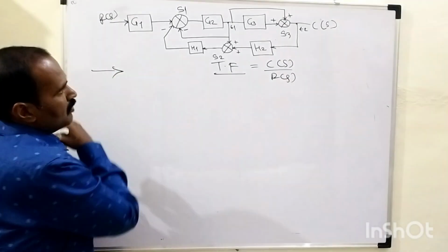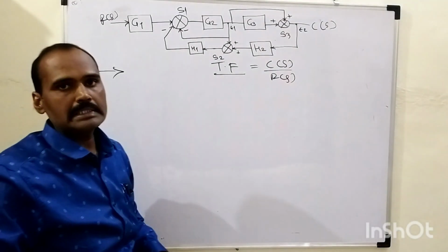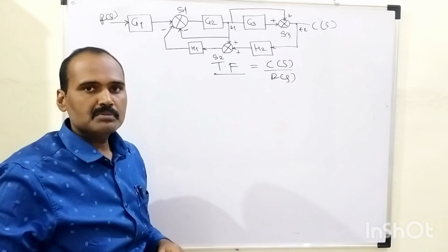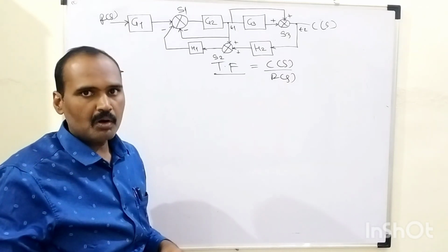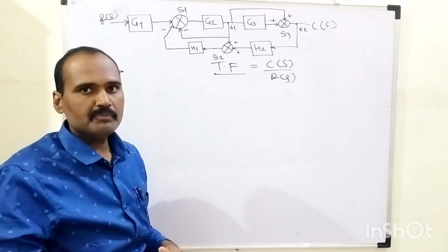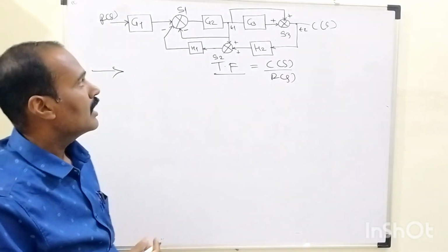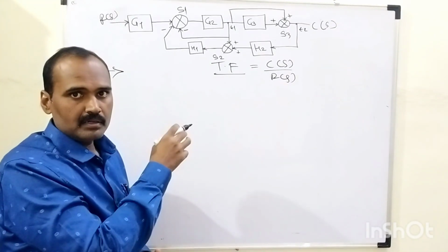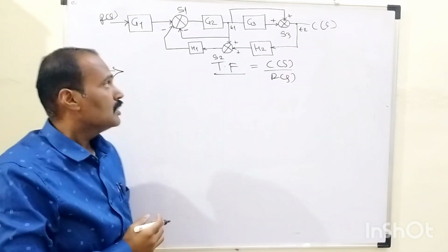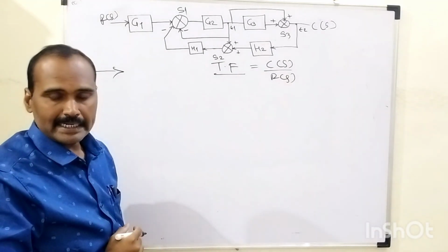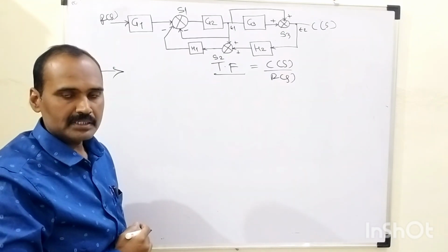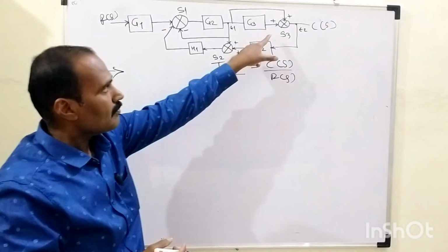So in that first step, what we need to do? We need to map this given control system with respect to those 8 different rules which we had discussed, right? Blocks in series, blocks in parallel, how to eliminate the feedback, associative law, right? And as far as the remaining 4 laws are concerned, those belong to shifting of summing point and takeoff point before and after this block, right? So out of those 8 rules, first of all, we need to map which rule is adoptable in that first step, right? So it is very clear that we don't have any blocks connected in series form, but surely we can adopt the strategy belonging to reduction rule number 2, because as you can see, as far as the summing